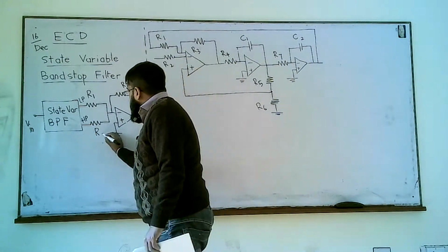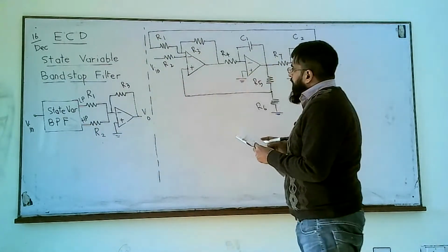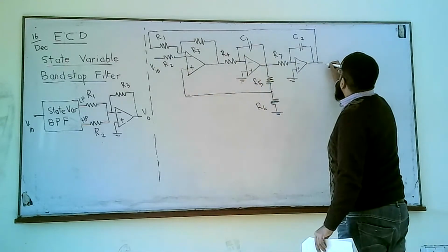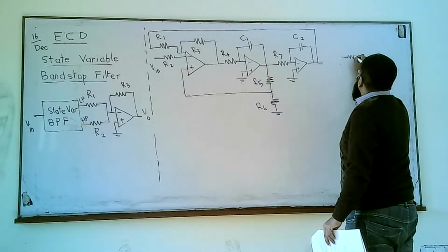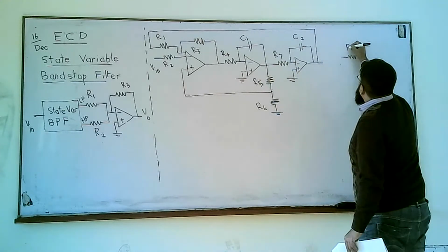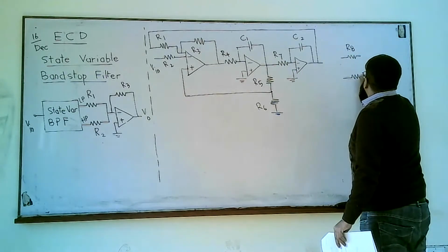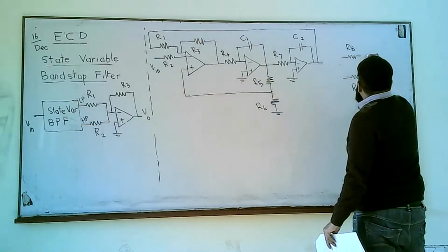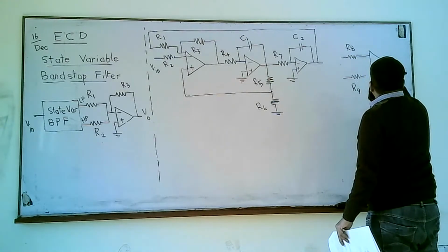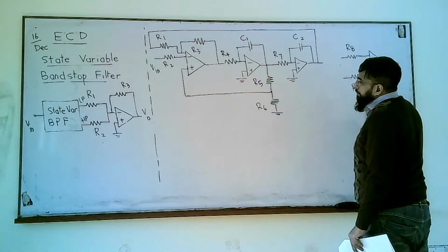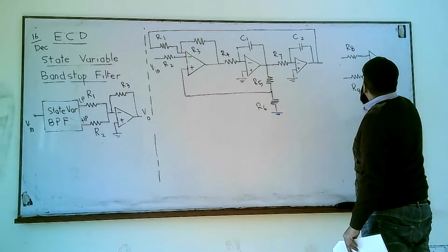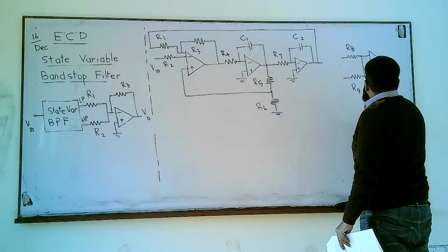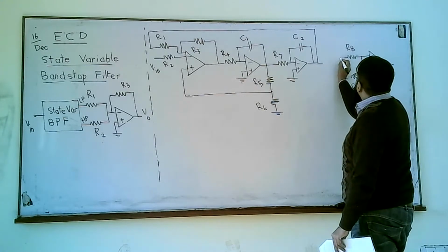Resistor, we need two resistors, R1 and R2. So let's rename those because we have already used the names R1 and R2. Let's rename these resistors: R7, this should be R8, and this should be R9. And then we have this inverting amplifier implemented. Negative, this is positive. Actually, they are the same. Positive, this is grounded. So this is an inverting amplifier.